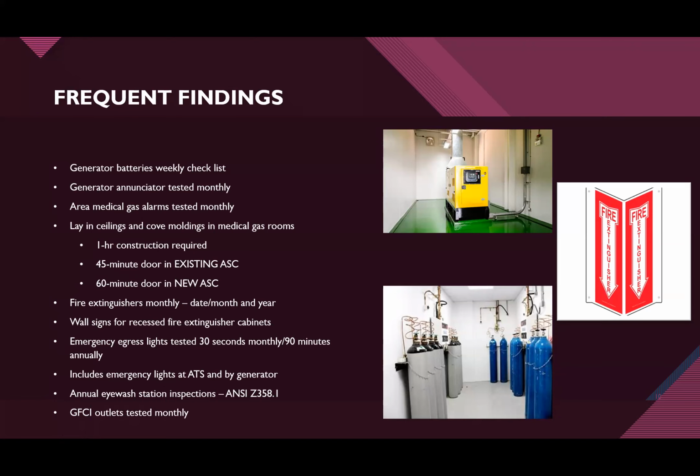Annual eye wash inspections. Most of the places I go, they have the eye wash station in the decon room, right? And so ANSI Z358.1 2014 requires annual eye wash inspections. And so potentially that includes temperature, but it always includes flow, and it always includes cleaning of the eye wash pieces itself. Bottles are never an eye wash station. Those squeeze saline bottles are never an eye wash station. An eye wash station needs to be activated in one motion for 15 minutes, hands-free. And the moment I have a bottle in my hand, I can't do it hands-free.